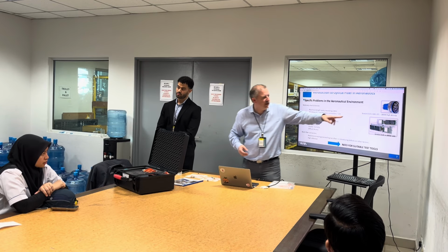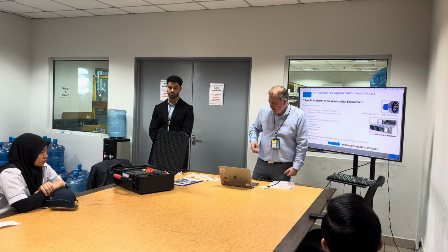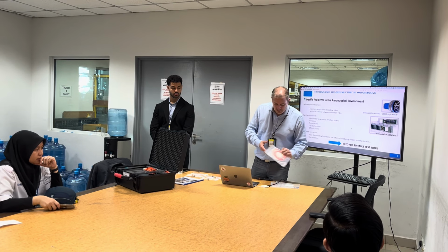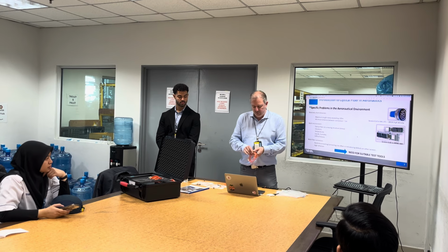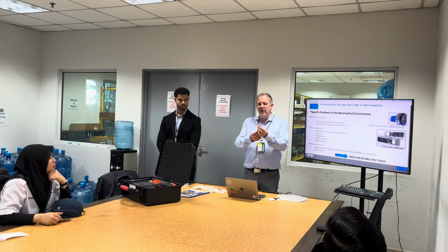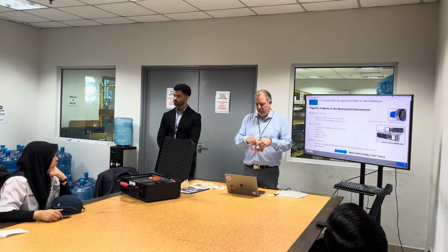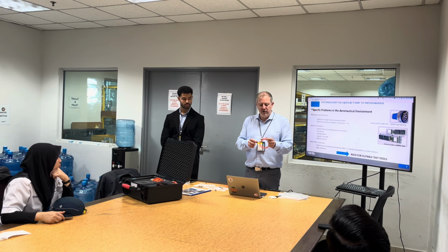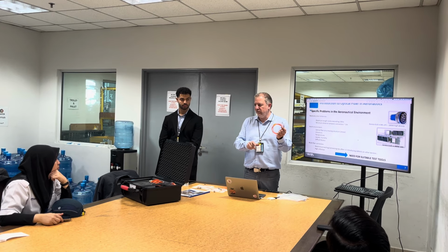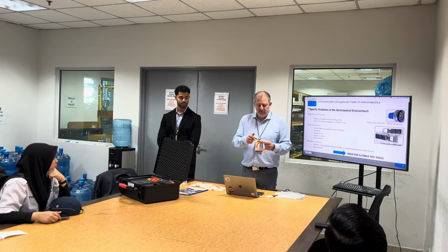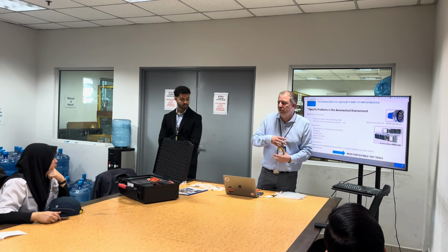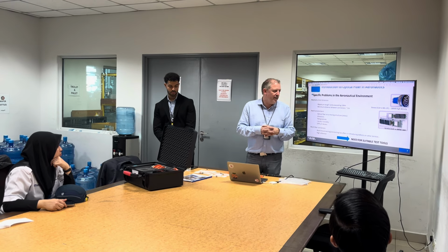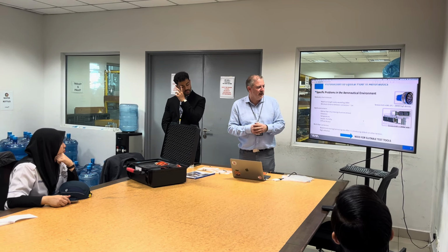So this kind of connector is the high density one. Otherwise, you can also find smaller connectors. This is one example here. This kind of connector is FC, a typical, very classical telecommunication one. I think this one is Helio, so that would be an Airbus standard, for example. So you have different connectors. These are single, and you have some high density with multiple fiber optics. I don't know if you have much of this, but in case, you could have this in the aircraft.